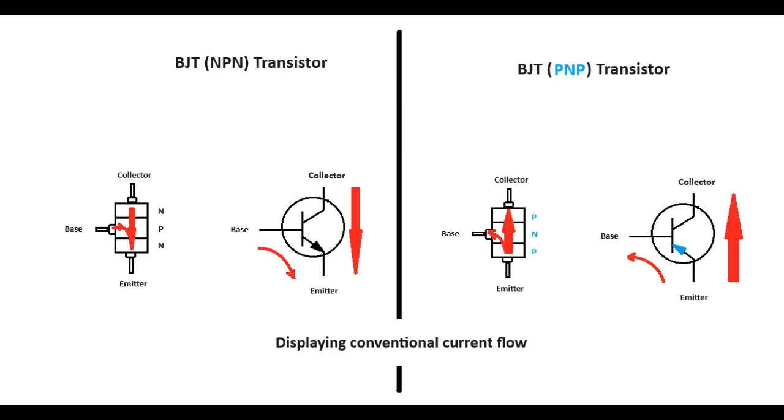You can't just apply any voltage or current to the base of the transistor and expect it to work. Internal to the BJT transistors are internal diodes that require around 0.7 volts in order to forward bias the diodes and allow the transistor to operate, essentially switching it on. The base of the NPN transistor needs to be connected to a potential voltage to allow current to flow into the device and be high enough to forward bias the internal diode, while the PNP works in the opposite manner, requiring current to flow out of the base and be high enough to forward bias its internal diode.